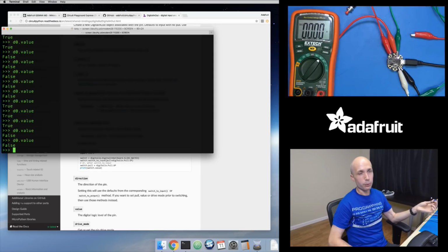Sometimes they require a lot of voltage, so you might need to wire up a transistor or a relay or something that can control it, given a small amount of current from your digital output, because the digital outputs on your board can only source maybe around 10 milliamps of current. You'll have to look at your board and the description of all the pins, but there's a limited amount of current, whereas some of these solenoids might require hundreds of milliamps or maybe even an amp of current if it's some really big beefy device. So your board's never going to be able to provide that much power.